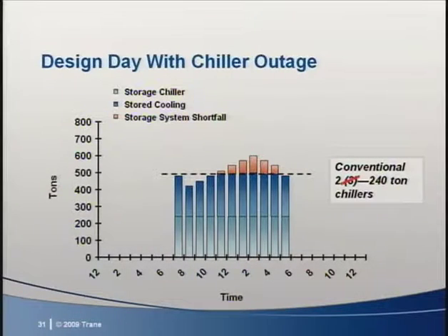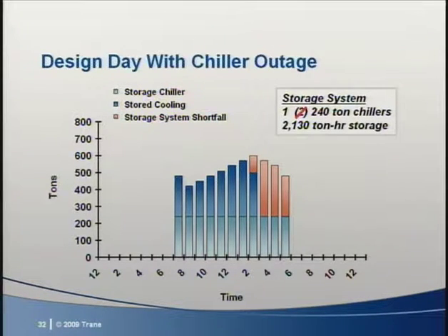One myth is that ice storage systems have less redundancy. Let's look at what happens during an equipment failure. If you have 3 chillers and one's unavailable, or if ice is unavailable, you'll be short cooling in 6 of 11 hours, shown in red. If a chiller is down but you have storage available, the remaining chiller and storage would be short capacity for only 4 of 11 hours. Or you could use the ice more slowly and have a similar situation to an offline chiller.